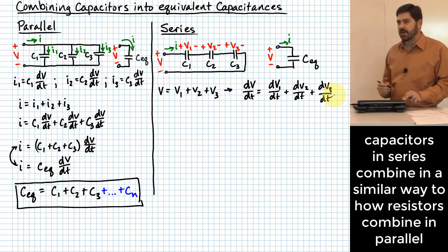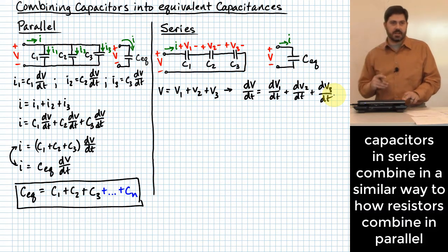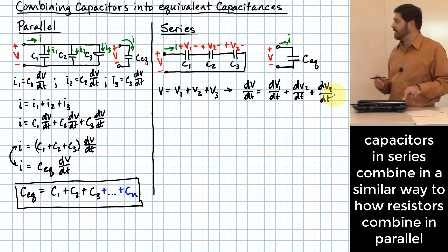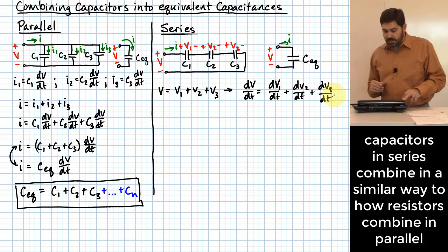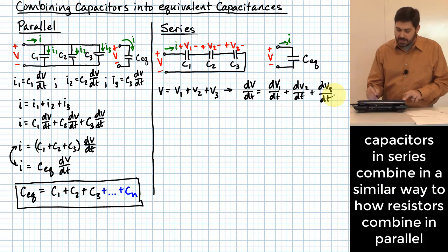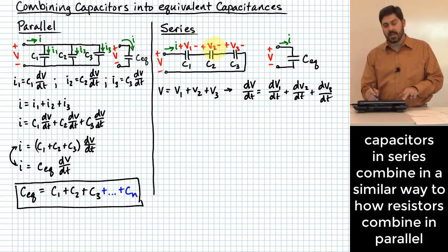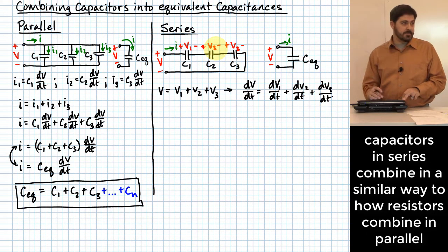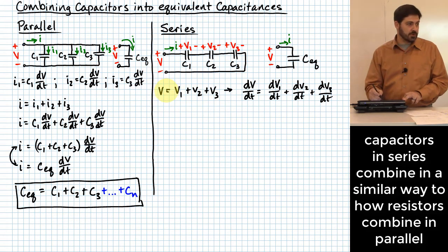Okay, and we'll pause on that for just a second, but this is an important thing to know that we can do that. What's a relationship we do have for a series circuit? We can't say all the voltages are all the same, but what can we say? The currents are all the same, right? So if we have I values, they are going to be the same regardless of where we look in this circuit, because there's no other place for current to go.